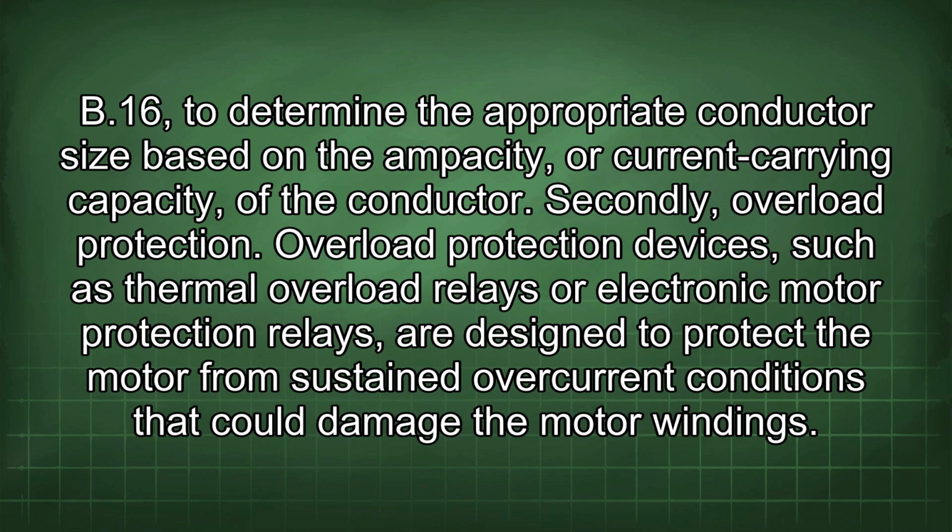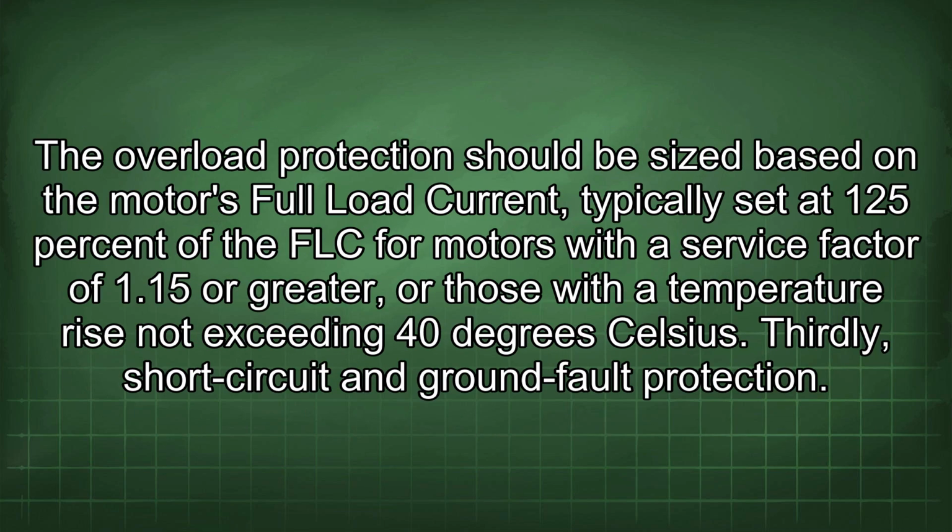Secondly, overload protection. Overload protection devices, such as thermal overload relays or electronic motor protection relays, are designed to protect the motor from sustained overcurrent conditions that could damage the motor windings. The overload protection should be sized based on the motor's full load current, typically set at 125% of the FLC for motors with a service factor of 1.15 or greater, or those with a temperature rise not exceeding 40 degrees Celsius.